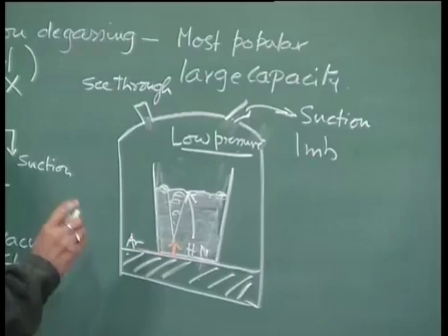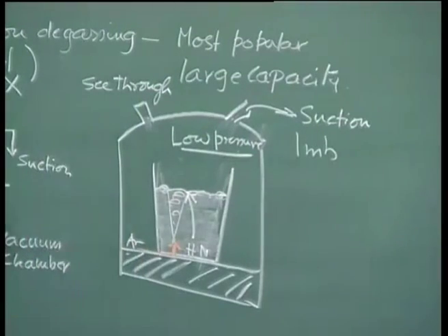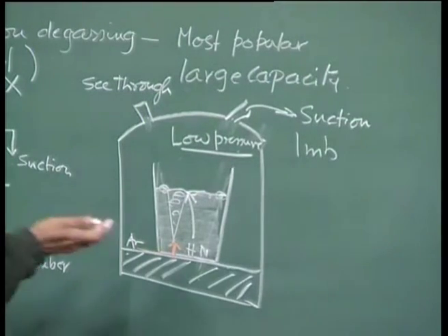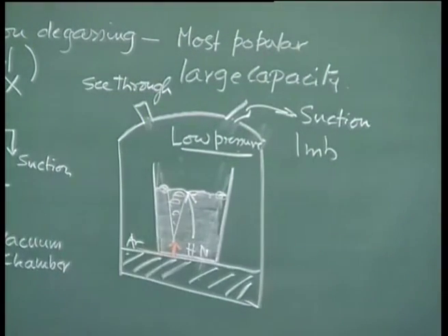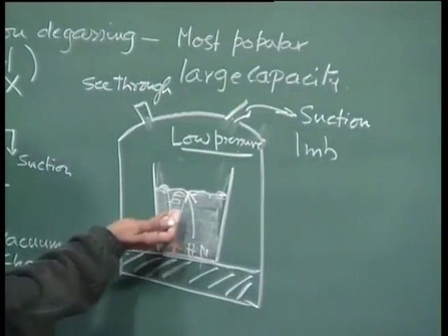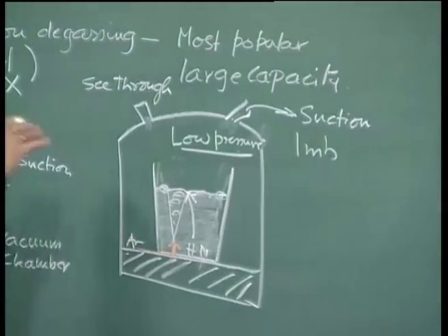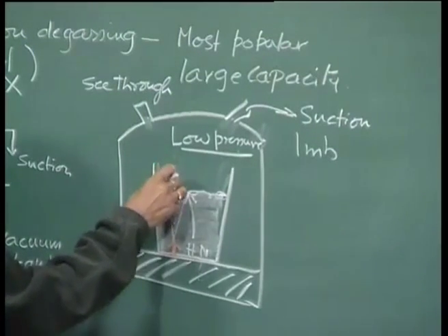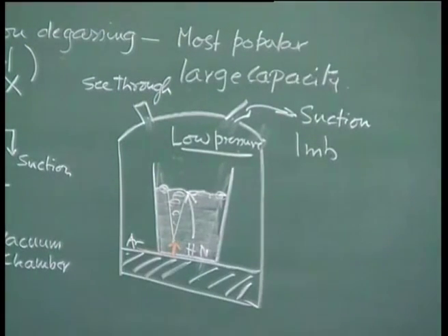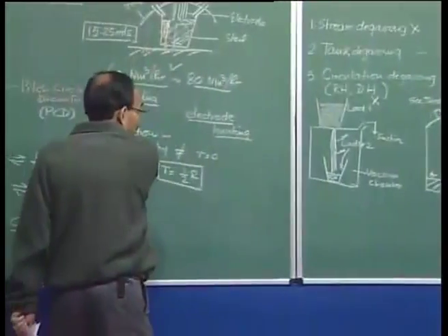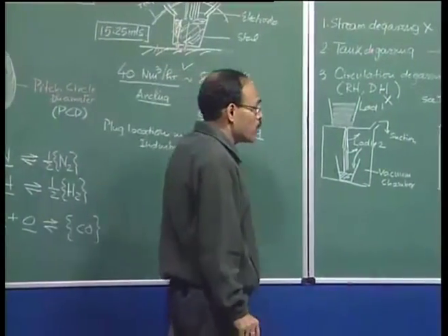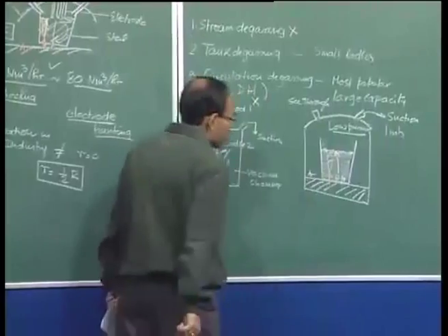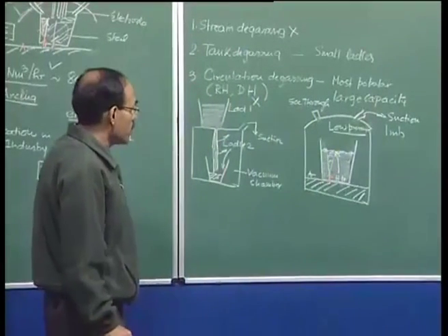So we understand that the injection of argon gas during the vacuum degassing process is extremely important, as it facilitates bringing fresh material towards the slag metal interface or the metal ambient interface, as a result of which fresh metal containing hydrogen and nitrogen is exposed to vacuum, and these chemical reactions take place, producing ultra low nitrogen and hydrogen steel.